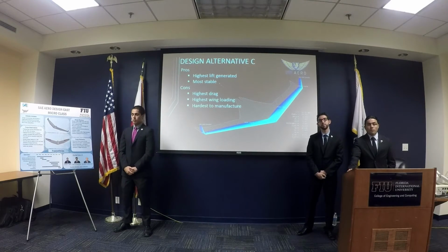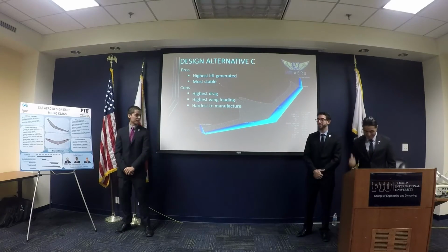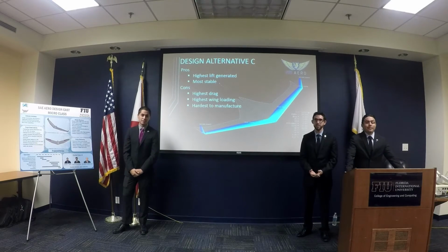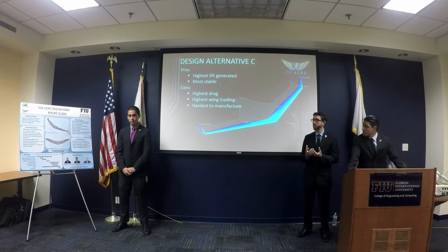Why a flying wing? Perfect question. I will take that one because I was probably the most opposed to the idea. You can have very efficient, let's call it conventional, airplane designs that can lift a lot of weight. However, a flying wing gives us two main benefits that nothing else gives us, and one is modularity. We can put it together really quickly. It's innovative, since there are only a few aircraft currently flying in the flying wing configuration. We're pushing everything outside of the boundary.